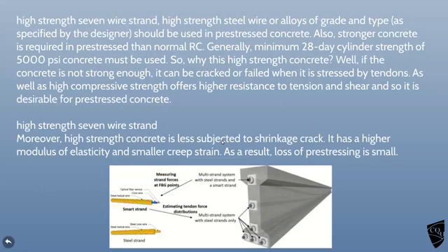You put high strength wire strand, or you can put bars, through the concrete. And this can be cast in concrete, and these would just be pathways that have been left. You could have put plastic pipe in the casting so they're ready to take the strands. Okay? So stronger concrete is needed for this pre-stressing, otherwise it would just crumble where you start to tension them up. If the concrete's not strong enough, it'll crack and fail. So you need high strength concrete.